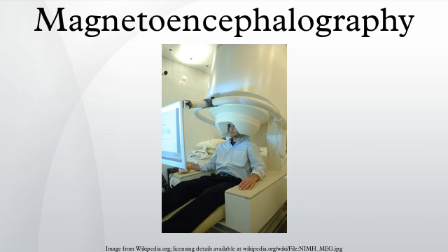Active shielding system. Active systems are designed for 3-dimensional noise cancellation. To implement an active system, low noise flux gate magnetometers are mounted at the center of each surface and oriented orthogonally to it. This negatively feeds a DC amplifier through a low-pass network with a slow fall-off to minimize positive feedback and oscillation. Built into the system are shaking and degaussing wires.